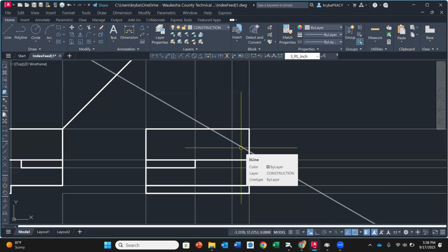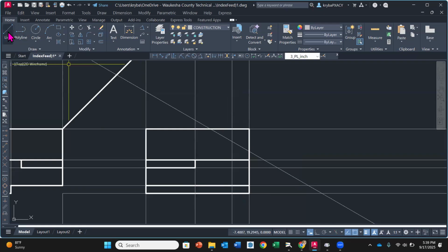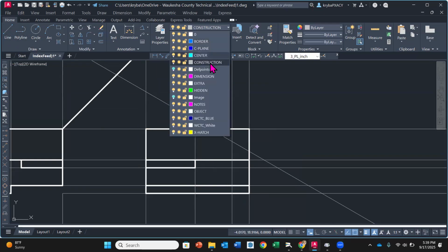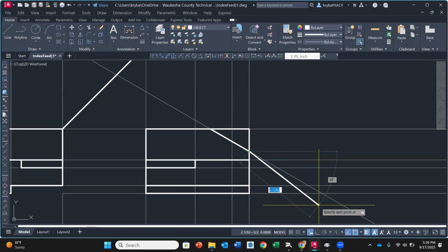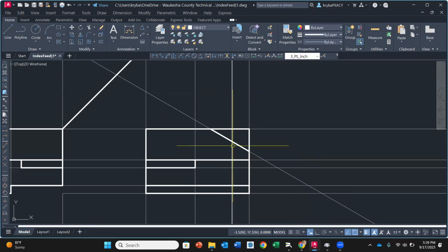All right. So then now what we're going to do is we're going to draw the line, oopsie, I gotta draw it as an object line. Draw the line from that intersection, and then it's gonna go straight back to the end right there. That's my 30 degrees. Now, this vertical line right here, that's that 1.25 edge.